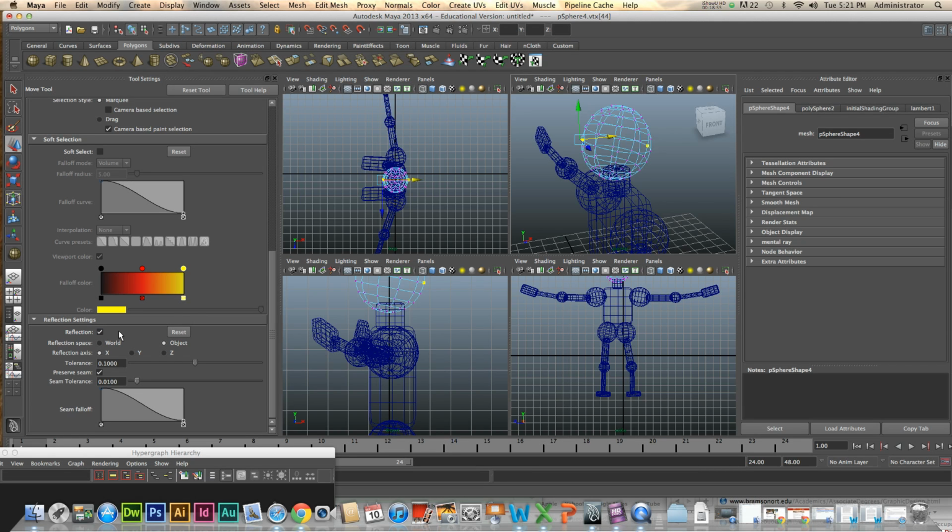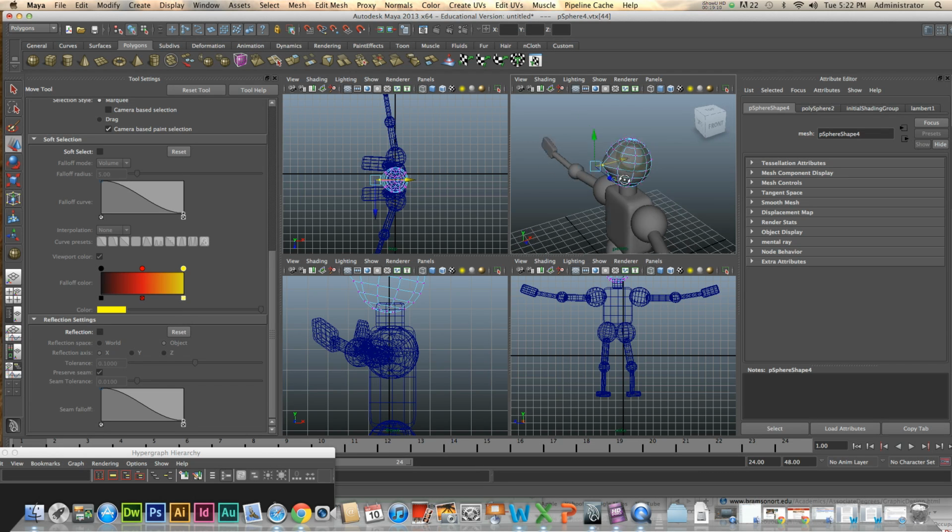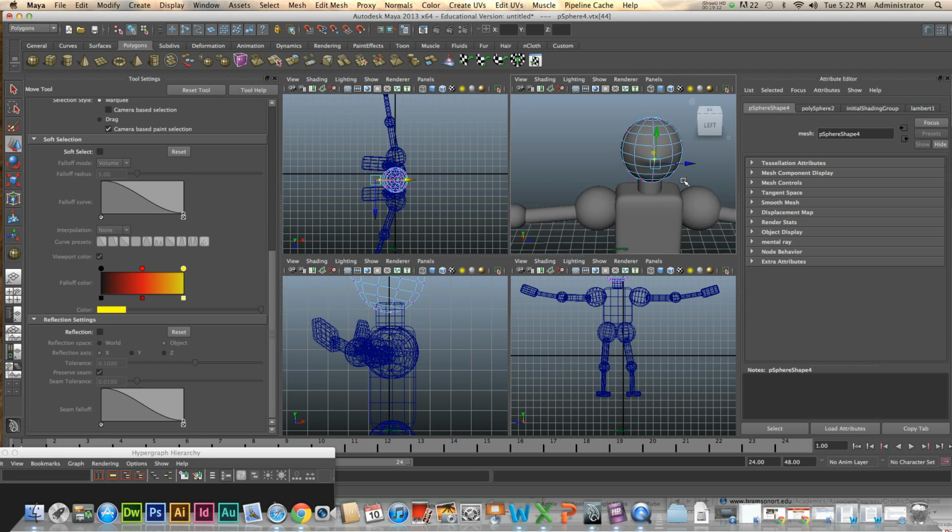It's a kind of mirroring. I'm going to turn it off, and this is going to get rid of my problem. So now when I actually click on the nose, for example here, go back to 5, which is my shaded mode, I can go ahead and just push out my little nose, and I don't have these problems anymore.